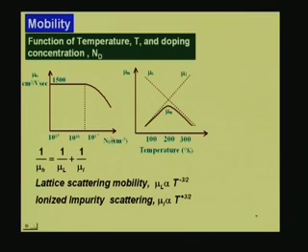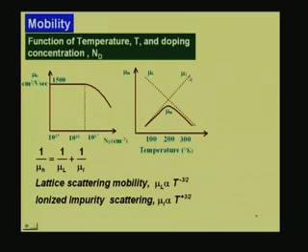Now, this particular value of 1500 that we have put here, that is the mobility at room temperature. So, if I take a look at the total temperature dependence of mobility, a qualitative picture I have drawn here. At lower temperature, mobility will be low, decided by this graph, this plot mu I. There are two graphs which I have plotted. One is going up, that is mobility mu I, which is ionized impurity scattering, that keeps on increasing with temperature.